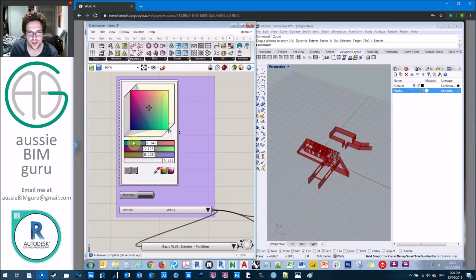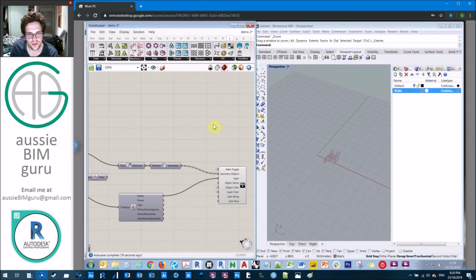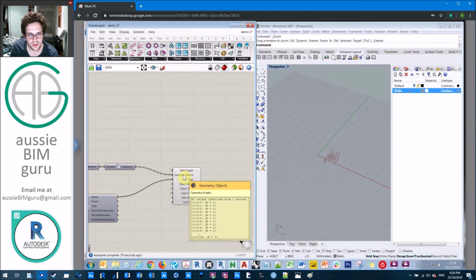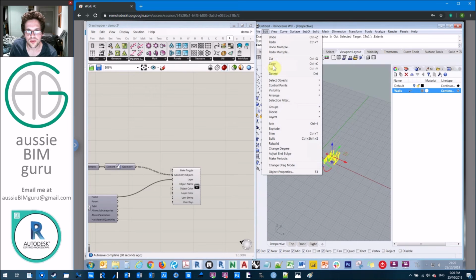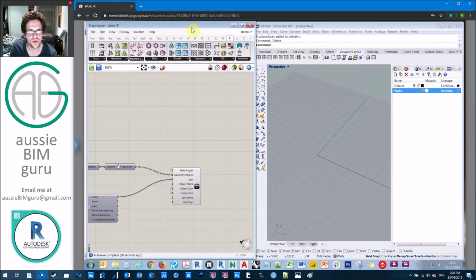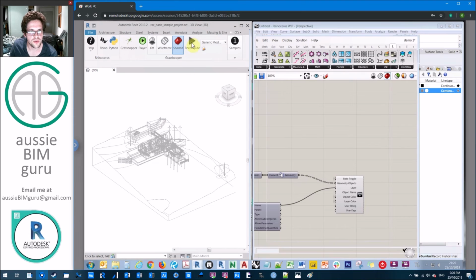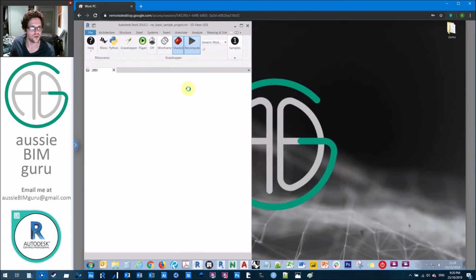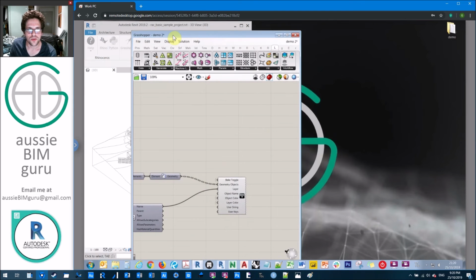So that's pretty exciting. I might just turn off the geometry preview because it's overlapping with what I can see. It's interesting, it's only baked a few elements. So it didn't seem to bake all of them. It seems like the filtering is still persisting. So what I might do is just recompute. I think my filtering is persisting, so I'm going to do a recompute, which basically says refresh my model, rerun the Grasshopper script in the state that it's in. So we'll try that.